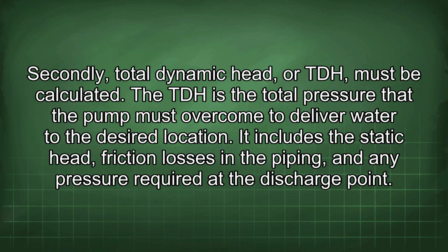Secondly, total dynamic head, or TDH, must be calculated. The TDH is the total pressure that the pump must overcome to deliver water to the desired location. It includes the static head, friction losses in the piping, and any pressure required at the discharge point.